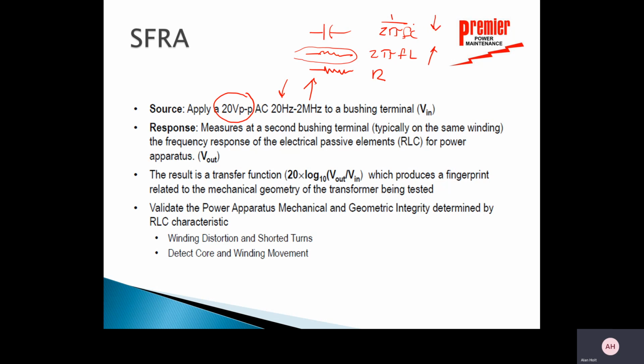So if you start looking at a sweep and you see basically a really strong signal coming back, so your dB losses are smaller. We talked about dB last week. dB losses are smaller at the lower frequencies, then I know that at the lower frequencies the path that circuit is taking is through the inductor, okay, because that would be nearly 0 ohms impedance. At the high frequencies, if I see a pretty high return on my input, I know that I've got to be dealing with the capacitive portion because that's when the capacitive reactance would be near 0.